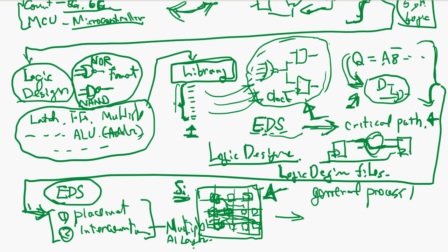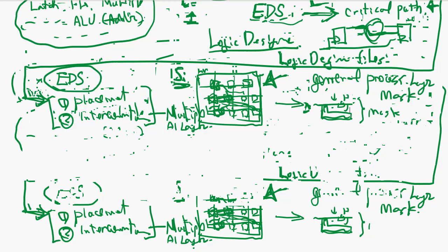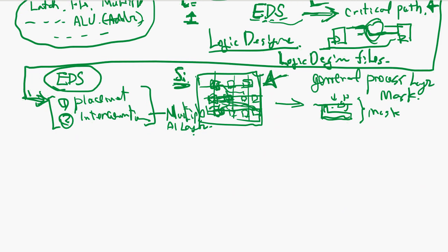Like if you put the transistor here, the cross section is going to be, it's a bipolar transistor, the collector, and this is p-type and n-type. Those are construction, you need multiple masks. Okay, this is called the standard cell design approach, because you have a library, standard cells in the library.